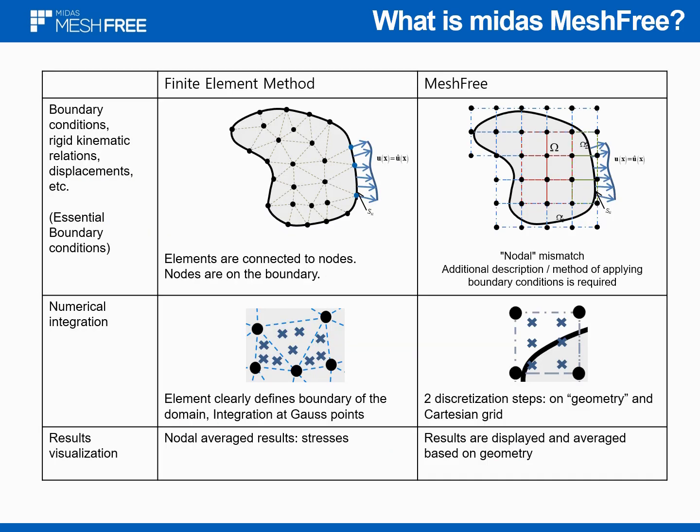Let's look briefly at key differences between FEM and MeshFree. The first one concerns boundary conditions and the method of application. We are talking about essential boundary conditions. Since the nodes are not reflecting the boundary in the case of MeshFree, the traditional methods used in FEM for applying boundary conditions cannot be used, and therefore other methods are required.